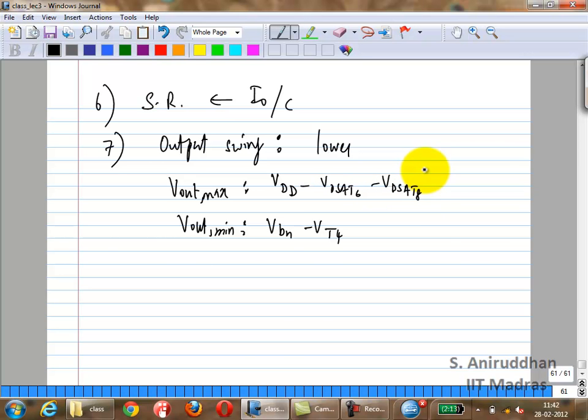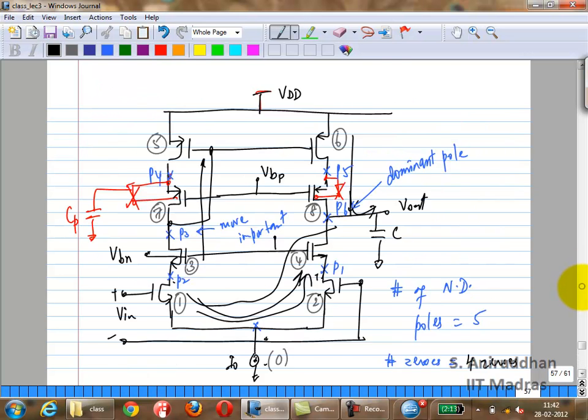Because the one difference is, on one side you have the current mirror, right? The current mirror, because it's a DC biasing circuit, you know you can bias it such that you have minimum VDSATs for the two devices. Correct? So you can bias the current mirror such that these two guys both have just VDSAT minimum and things will work fine.